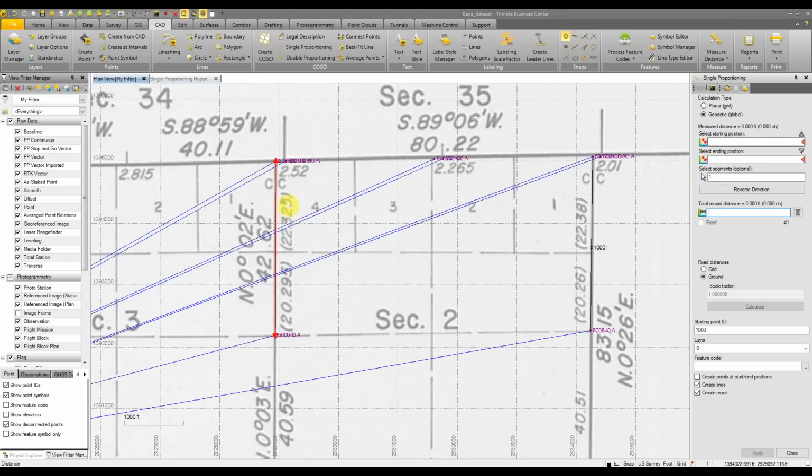And then we have our right side up triangle for the start, upside down triangle for the end. So it's going top to bottom. Boris teased me when we did a practice run of this that I went from bottom to top, so I made sure to do it the other way around this time. So we got 22.325 chains for our first record distance, tab or enter to get down to another line, and 20.295 chains for our second distance.